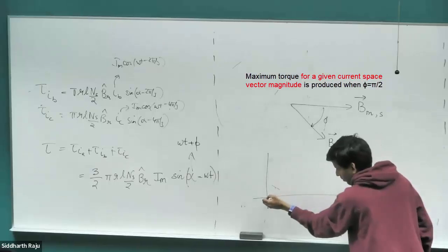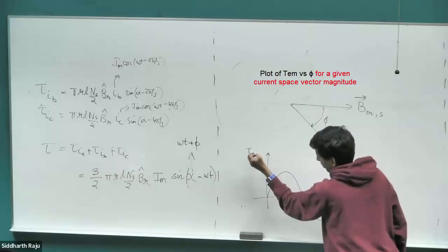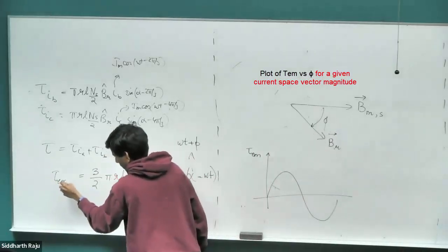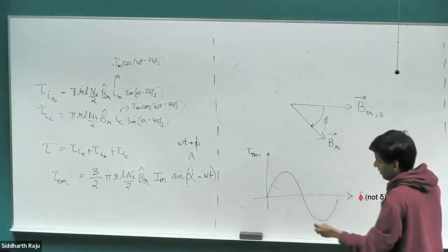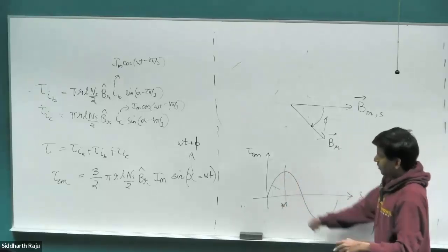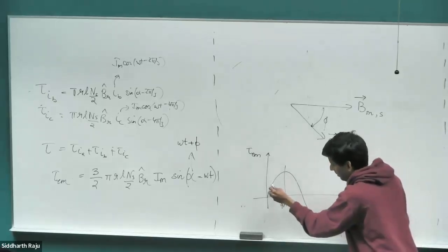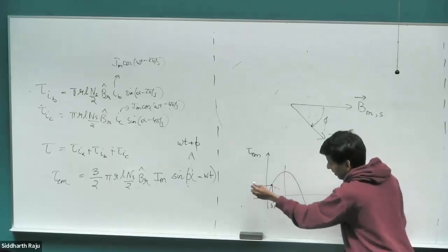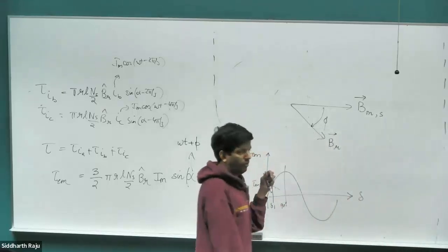So if you look at the motor, this is going to be our total electromagnetic torque, tau m. And that is going to vary as a function of delta. As this angle goes to 90 degrees, that is when you will produce the maximum torque in your motor. So let's look at what's going to happen. Let's say we are starting, initially we are at some angle delta 1, and the torque is some Pem1. And as soon as I apply an additional load torque, what is going to happen?